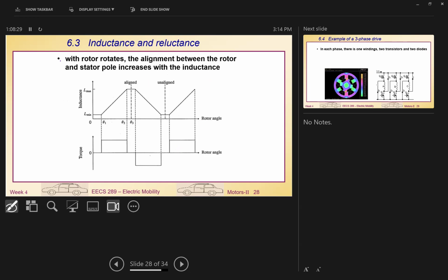So the equation we found is that the magnetic torque is proportional, in a way, to the change of inductance. When you have a change in inductance, then you can produce magnetic torque. When it's fully aligned, we don't have magnetic torque because there's no change in the inductance. So that's why this kind of motor relies highly on the variable inductance, or variable reluctance.